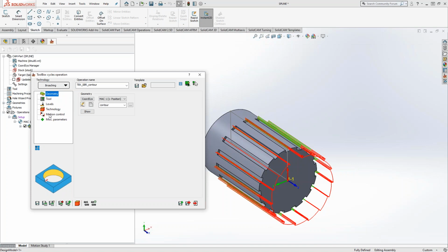So you can use a turning toolpath to just go in a straight line. Now this might require a lot of post modification. So you'll have to check with your post writer to see if it's even possible to do that with your machine. But if you were literally just typing out code, you would have the ability to tell it to not spin and then to just move in a straight line. So broaching is literally just moving in a straight line.